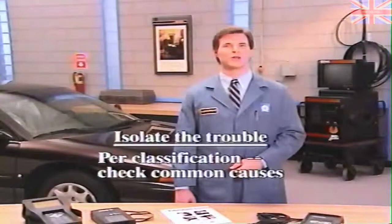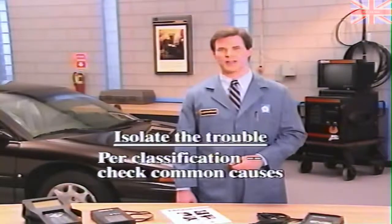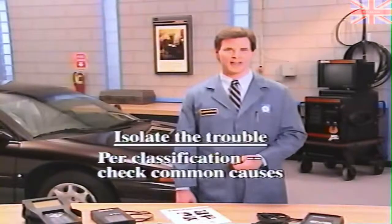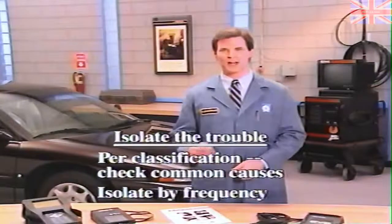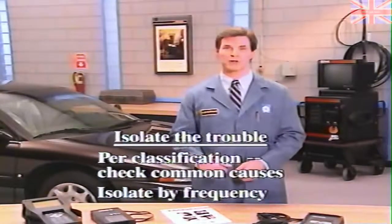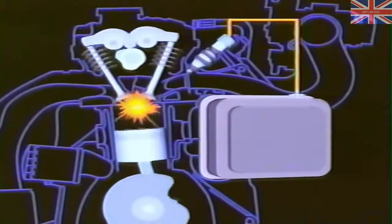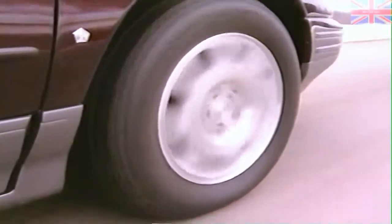By placing the noise, vibration, and harshness symptoms into specific classifications, you can then check various components and isolate the trouble. Another and sometimes quicker way, especially with vibrations, is to isolate components by matching the vibration frequency to the component frequency. In front-wheel drive vehicles, there are two major rotating component groups, engine and the driveline wheel assemblies.